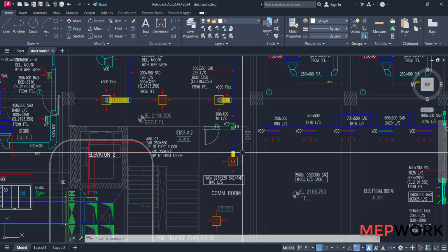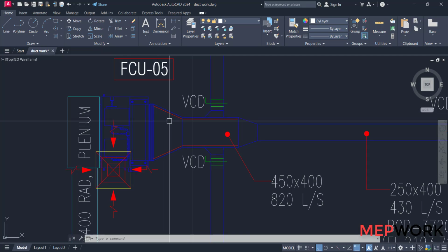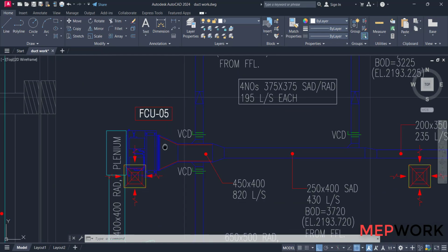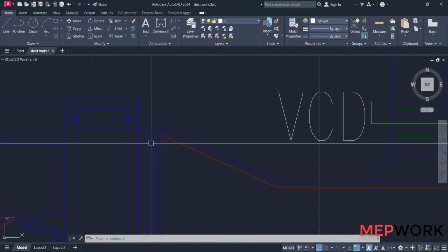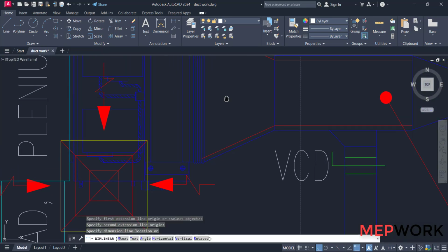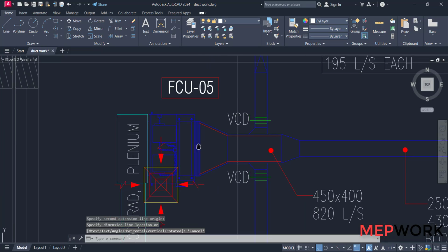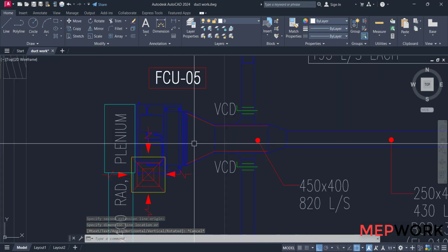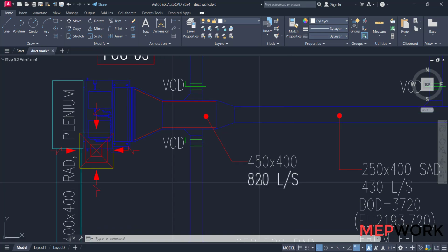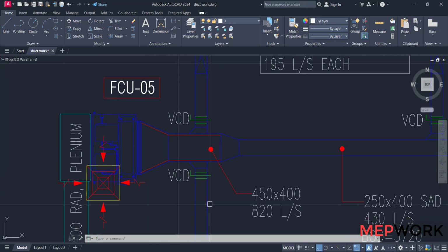This is the critical path, as we said before. And this duct starts with a fitting. So we will assume this is a duct, and this is the fitting. This is a flexible connection and its size will be about 850, and the depth of the duct will be about 200 millimeter and the flow will be 820 liters per second. And assume the length as 100 millimeter.